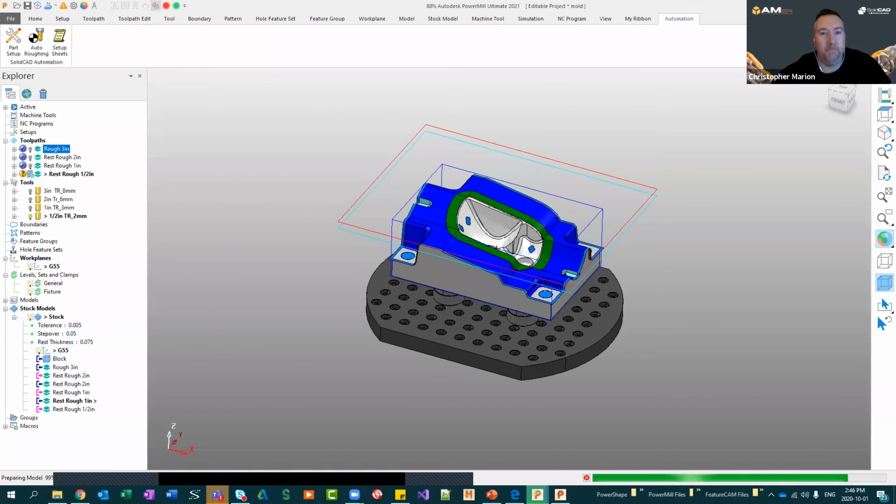So I suggest starting slow, get acclimated with it, read through it, because again, it goes from 0 to 60 rather quick, but it's definitely readable, and it's a very good assist as well. And there's also in PowerMill a location to grab all of the PowerMill parameters as well. So if you're looking for a particular parameter in PowerMill, maybe something along the lines of a certain toolpath thickness, you can run through this reference and find that exact parameter that you're looking for.